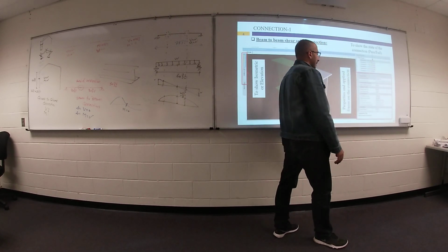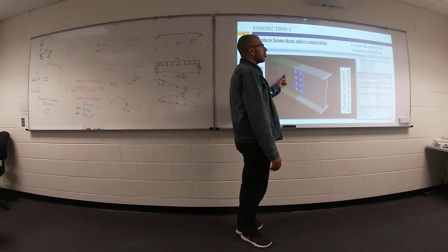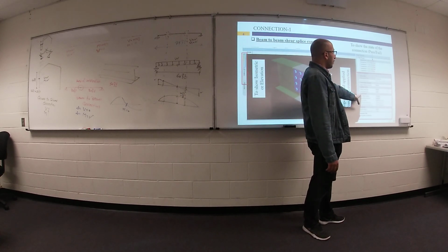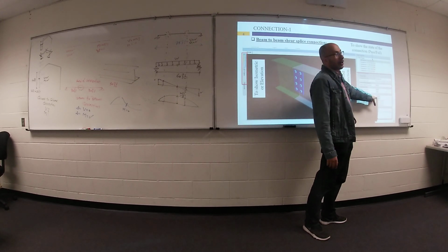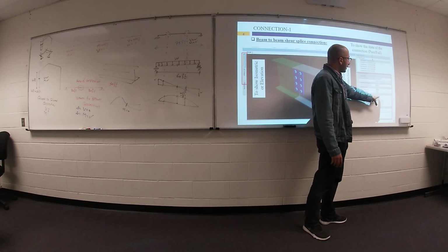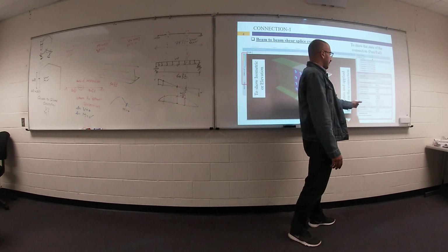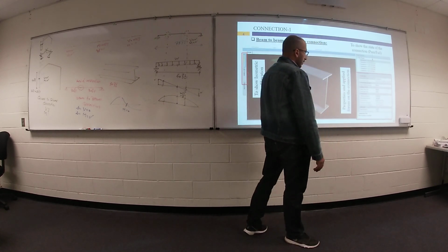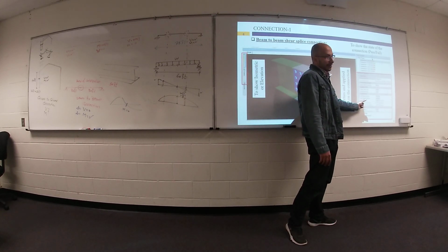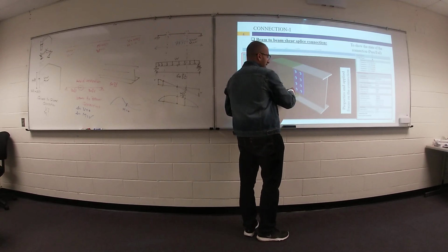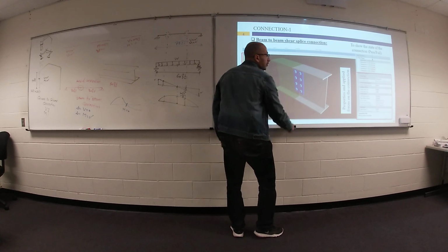For this one, I can choose the cross section of the left beam, a component of your connection. Left beam section, you can select the cross section of your beam. In this case, it's W 16 times 36. What is the cross section of your right beam? And also, you can figure out the dimensions of your plate. What is the width? What is the thickness of your plate?